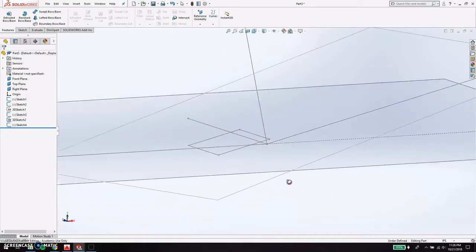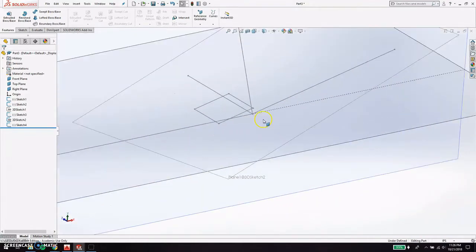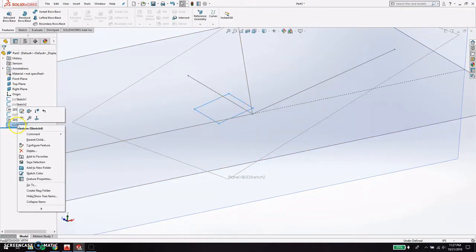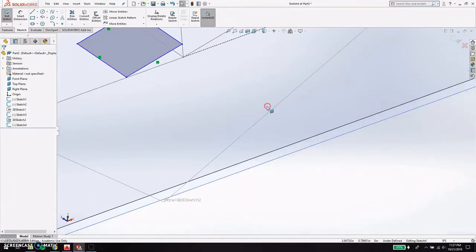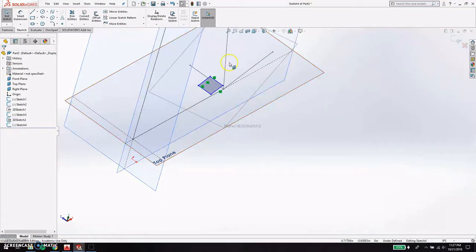The way that we're going to fix that is, let's take a look at our sketch again, this sketch right here. I basically want to edit this sketch. It won't exactly let me move things around when I'm not in sketch mode. So the way I can edit this sketch is by going into this area here, and this little thing with the pencil is Edit Sketch. So yeah, let's go into here and make sure that we're looking at this correctly.